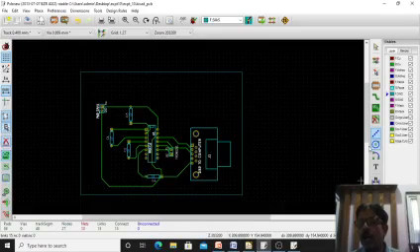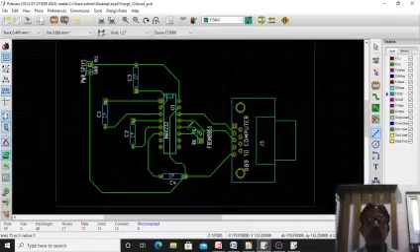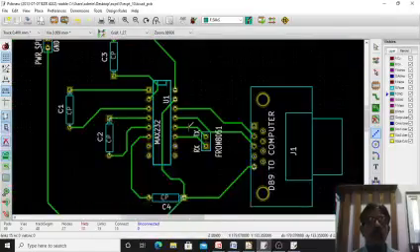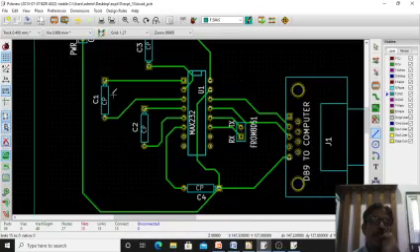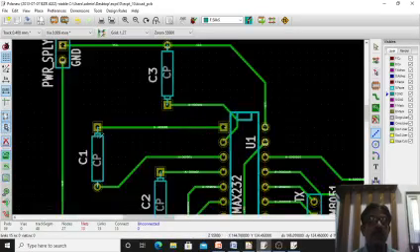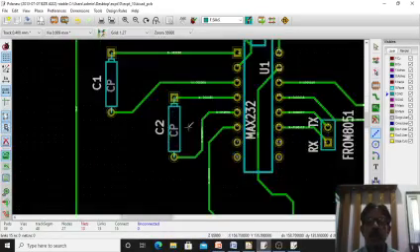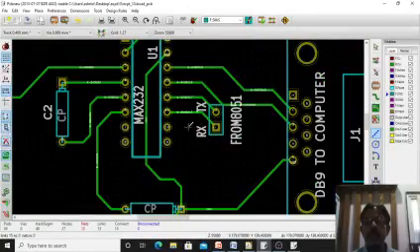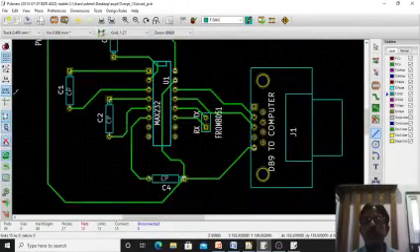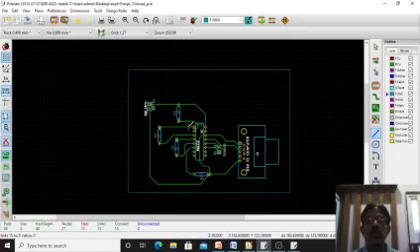And another optional step is there. I want to give some name to this PCB. Okay, this is my PCB layout I have designed. You can see here. Okay, this is the RS232. This is DB9 connector. All the 4 capacitors are there. Here C3, C1, C2. You can see all the tracks I have placed properly. Okay, you can see here. Okay, so last step is to give the name.